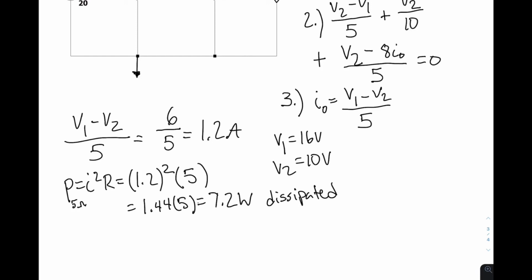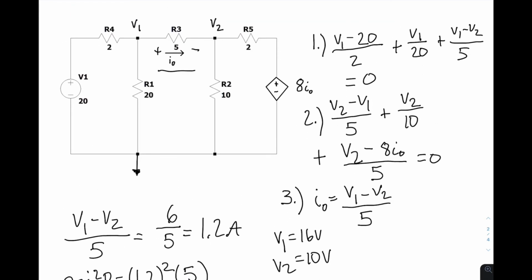A good exercise to build your problem-solving skills would be to switch the reference node with V2 or V1 and try to solve it that way. You'll find that it might make it a bit harder. Either way, it's good practice. This concludes our video on nodal analysis. Be sure to check our next video about supernodes when a voltage source is connected between two essential nodes.